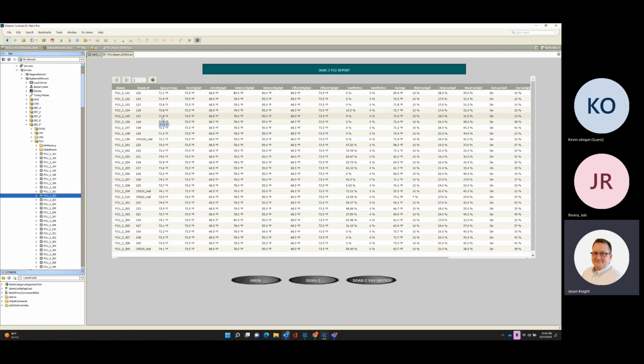and a half to get to set point this morning. It has an optimal start-stop algorithm that looks at every one of these. They all have their own. And 2105, man, it took an hour and a half to get up to set point this morning, but all the other ones, they were up to set point within 15, 20 minutes. So 2105's optimal start-stop program will calculate an earlier start for tomorrow.